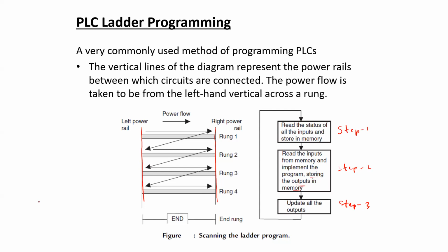Now, after drawing the set of instructions, while finishing the program, the user should enter this particular block, end or return, so that the CPU can understand that it has to start from the beginning again, and this process will go on. So continuously the inputs will be checked and the outputs will be updated accordingly, and unless the user interrupts the power supply or intentionally stops the process, this process of scanning will go on.